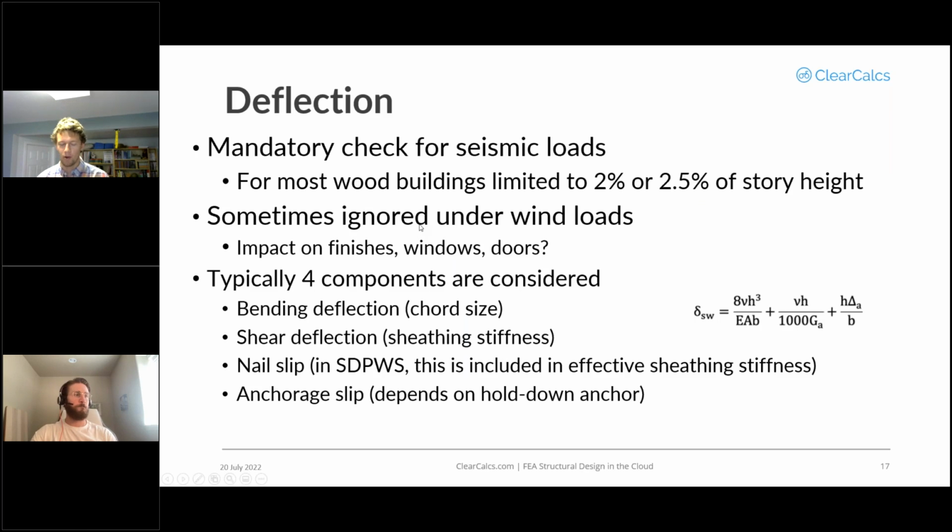A really interesting point about sometimes wind loads govern over seismic loads. One thing to be aware of, however, is when you're designing in high seismic categories, there may be some specific detailing requirements to achieve, say, ductility or more resiliency in your building, that even if your wind loads govern, you still need to have those detailing requirements. So just a side note, I want to make sure that we mention that. Yeah, appreciate that background, Laurent, and thanks again for that comment, Randy.